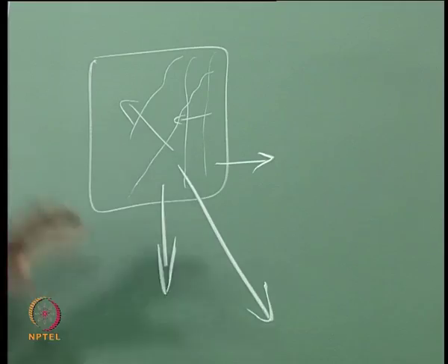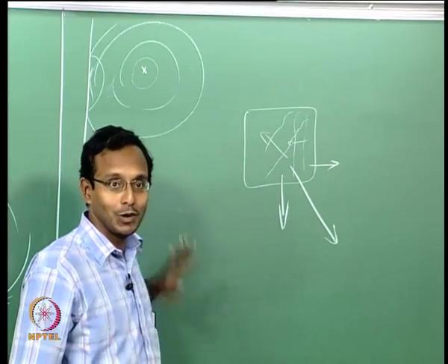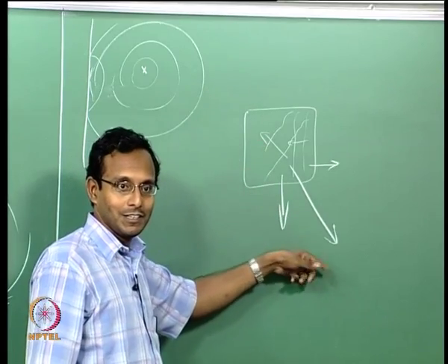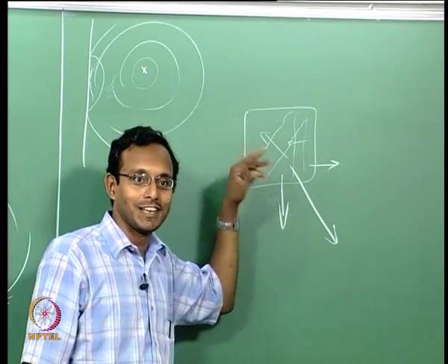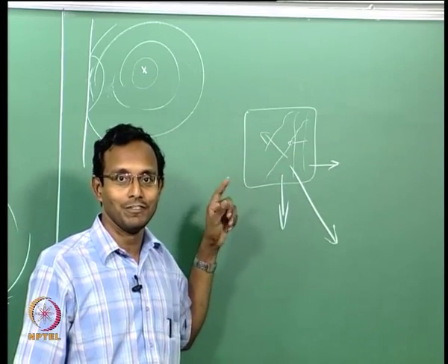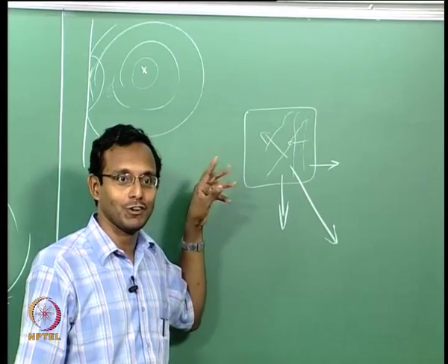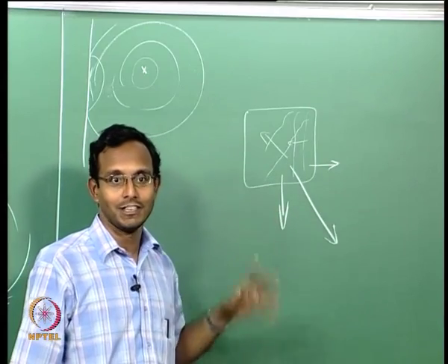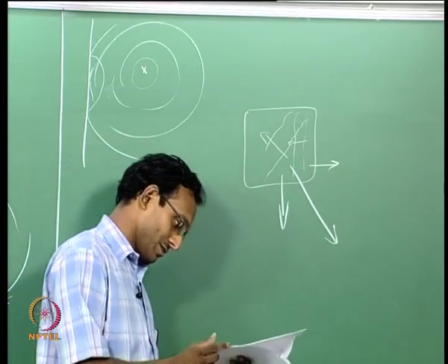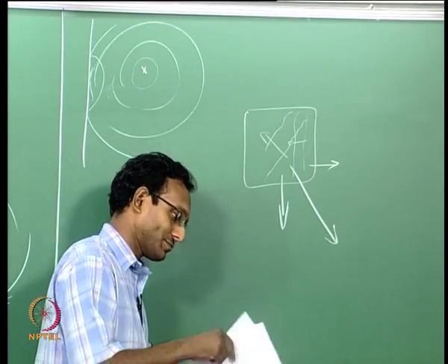So ideally the net velocity of this with respect to the outside reference frame is going to be the fluid velocity plus or minus, depending on the direction, the speed of sound locally. Or if it is a shock wave that is travelling, then you have to take into account M times a, not just a, the shock Mach number multiplied by a. All that should be taken into account.